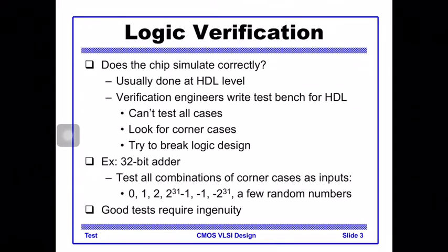If the chip has a lot of inputs and outputs, you cannot test all cases, so sometimes you test a certain number of cases. This can be random, or it can be the corner cases. The corner cases are like all zeros for the inputs and all ones.